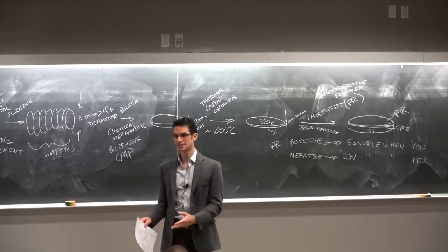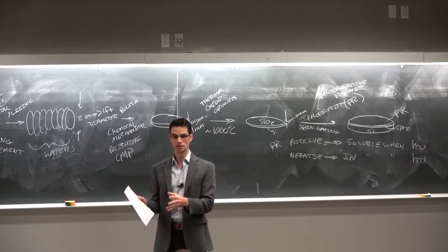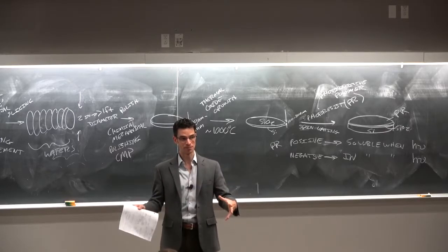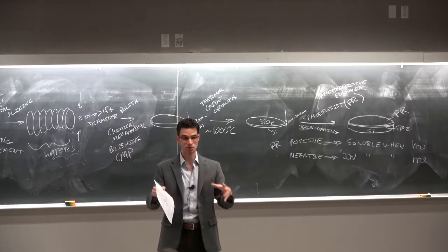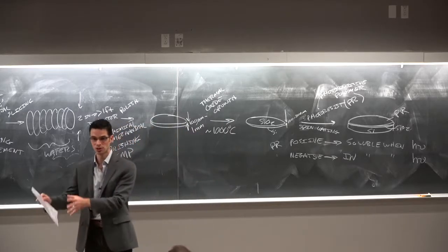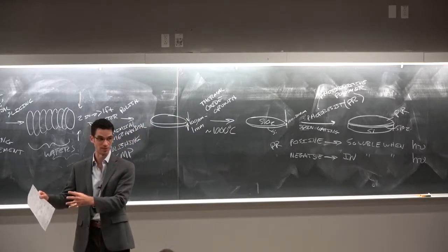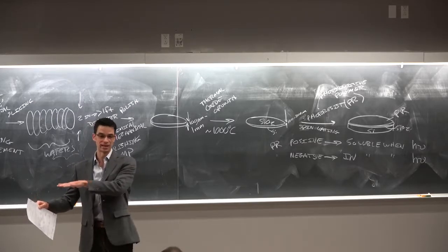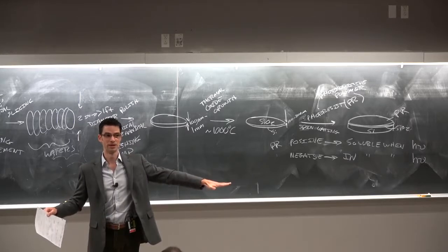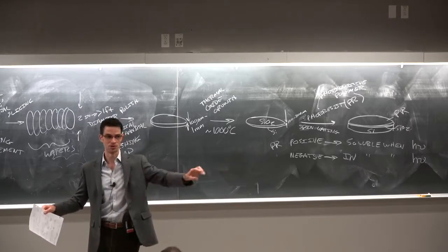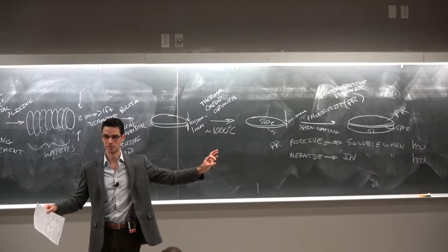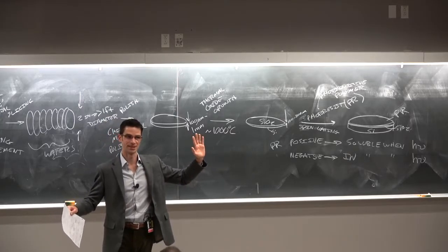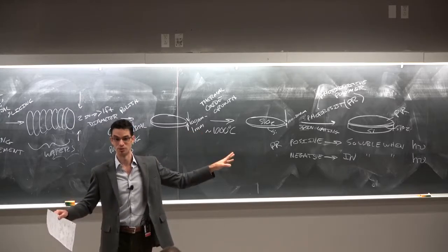But in either case, either spinning a neat melt of a viscous material, where the material you're spinning is pure, or you're spinning a solution of the material in a solvent, they both have the effect of giving you a completely uniform film up until the very edges, where you have usually a little bit thicker region called an edge bead, and those regions are usually not usable yet.